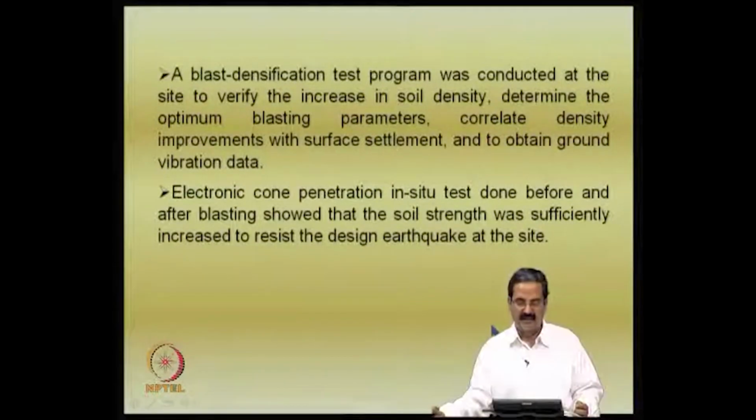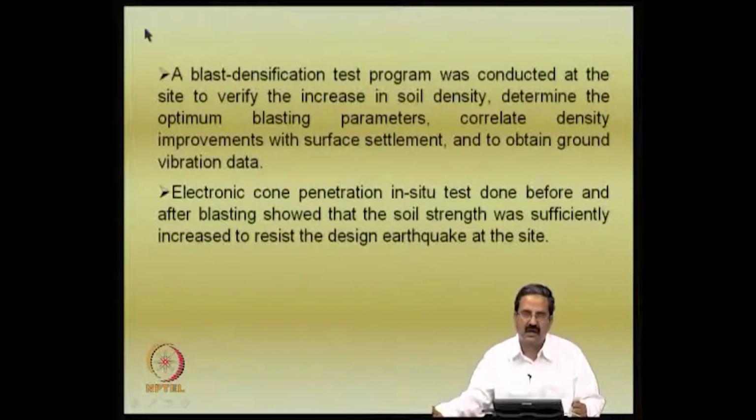So, a blast densification program was conducted at the site to verify the increase in soil density, determine the optimum blasting parameters, correlate density improvements with surface settlement and obtain ground vibration data. In fact, particularly when you do blasting, the problem is the propagation of waves, and it should not cause damage to nearby buildings and facilities. Blasting may be useful to you, but it should not lead to problems for the neighbors.